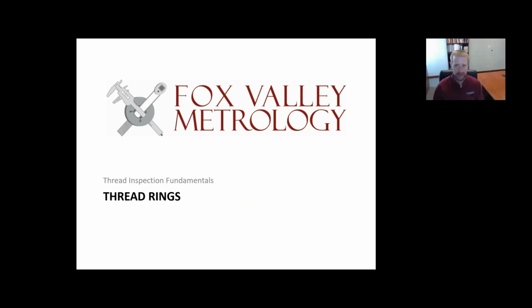So with that, why don't we dive into our discussion on thread rings? Thread rings are often sold as sets. Instead of how they were done on the thread plug side of things, obviously there's not really a good way we could put a handle onto 2 thread rings. So they're often sold as a set. One is a go and one is the no-go.